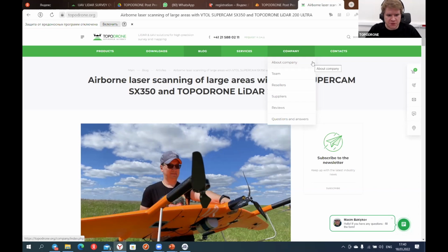Are there any features in MetaShape for transmission power lines? Yes, of course, in MetaShape there is a very good solution to detect power lines. But what I would suggest, if you fly over power lines with a photogrammetry mission, is that you will need to fly with less speed. You will need to fly a minimum of 4 lines to make an image alignment. And data processing depends on the quality of photos, the reflection, and the light conditions.